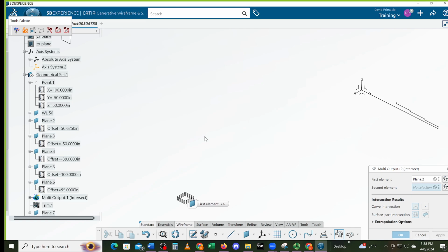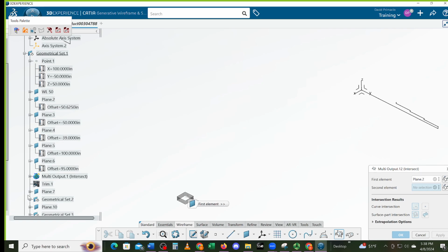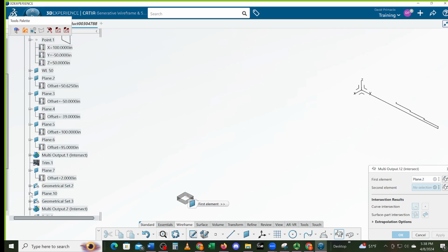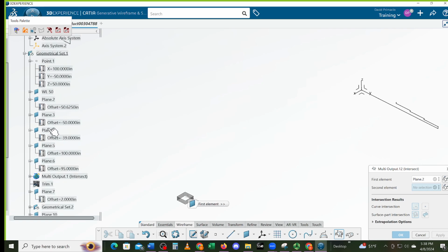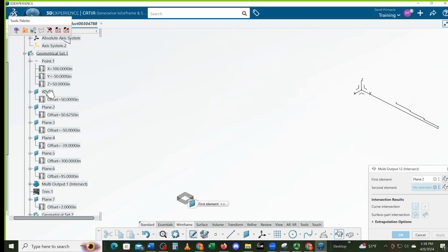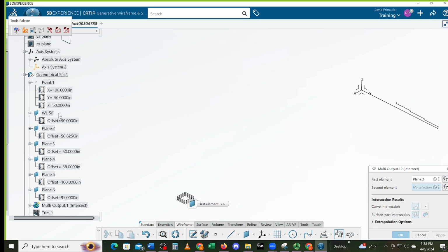Sorry. I'm intersecting the top plane to this buttock line, which is left buttock line 50. This one here, right? That's a water line. Oh, that's waterline. Waterline, I actually named that one. It's a negative 50, for the negative offset. 50, that's right. Thank you. Thanks for your help. Select OK.